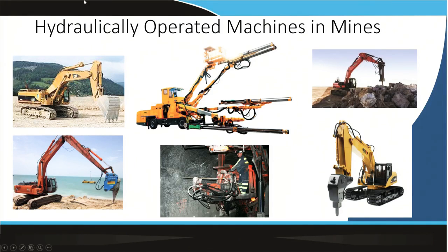You might have seen this excavator; we call it a hydraulic excavator. Here the whole operation, that is the propelling operation of the crawler, then the steering operation for taking directions, then the swinging operation, where the whole superstructure of the machine revolves around, is also given hydraulically.